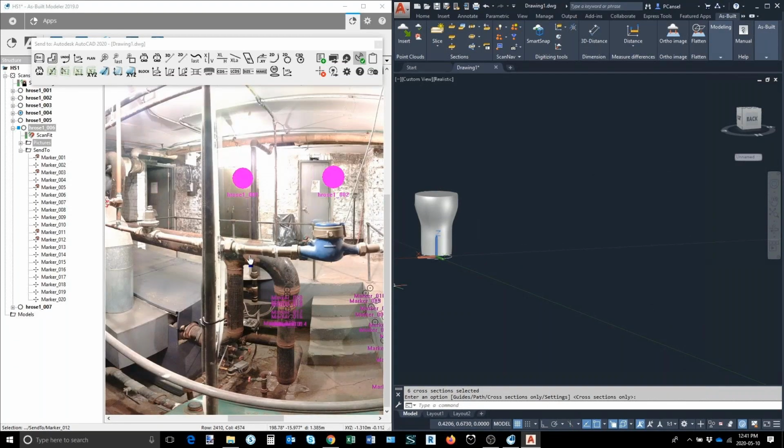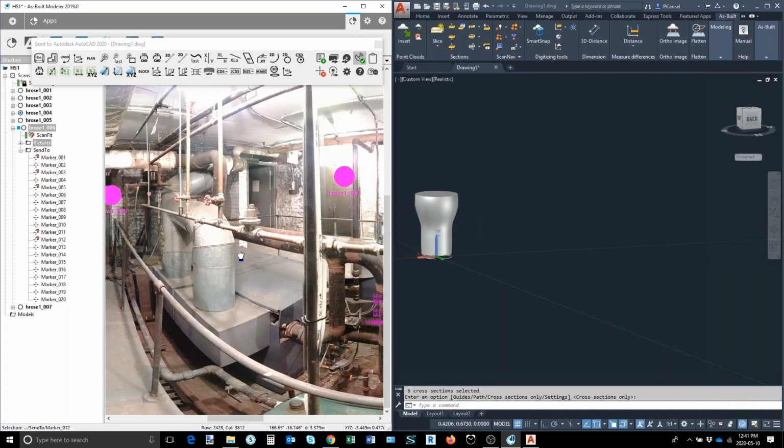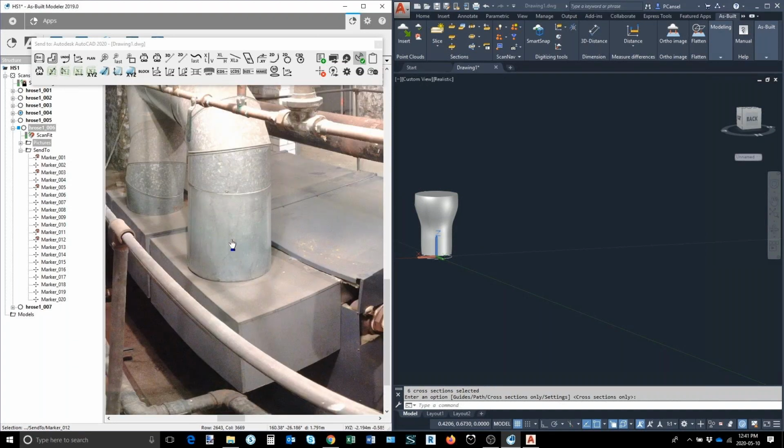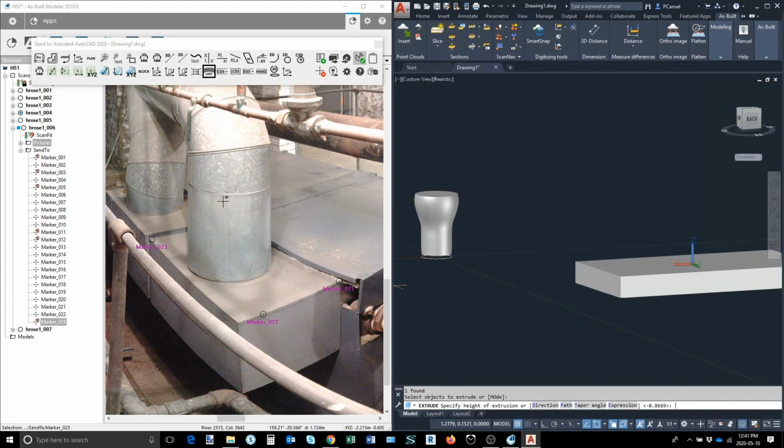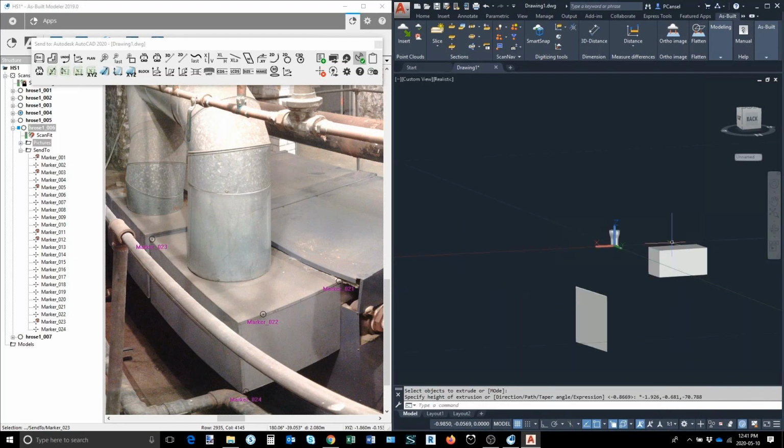Another very nice example I can give you is where you are hanging cables, or irregular pipes that are bending. It might be difficult. So first I'm trying to model the cube shape underneath. We have a command called rotated rectangle, where I make 3 clicks to model the base, and I'm adding the extrusion part to it. So I modeled the base part very easily with a few clicks.